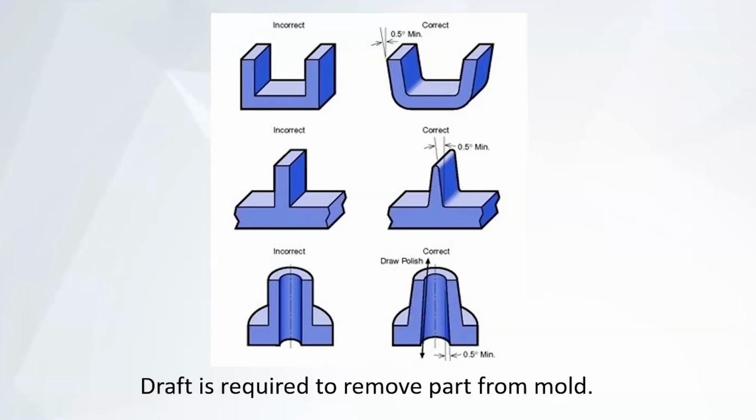This is normally not something I recommend doing on your initial design when you're prototyping, because adding draft just complicates the model. It makes making any changes to it more complicated. And fortunately, draft is something that you can easily add to the design after you've finished prototyping. Draft isn't something you typically have to think about too much up front, versus undercuts and uniform wall thickness and all the other issues that we'll get into, which are things you need to design for from the very beginning.